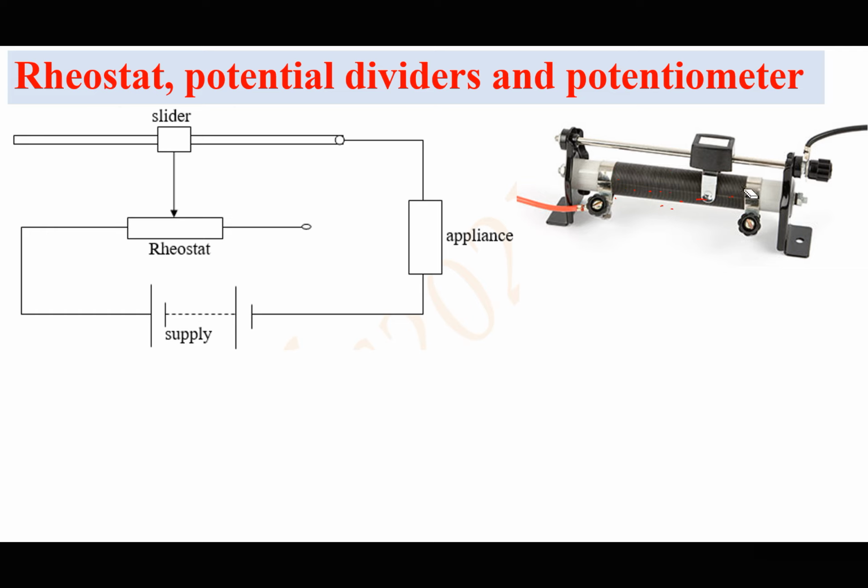If you recall very well, the circuit symbol for the rheostat, we said the rheostat could be drawn as a fixed resistor like this one, and then we drew something like this. So this was showing a sliding contact, that the sliding contact would be moved along the length of the wire, which length of the wire is acting as a rheostat. So this is how the rheostat is going to work as a potential divider.